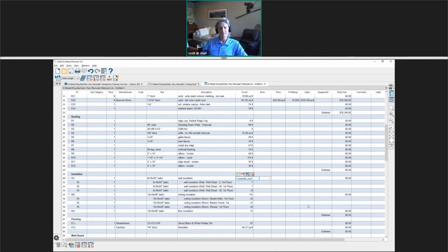And if you notice, once you do that, so let's see, what's the length in this case? Is it the 93 inches? Right. Yeah, so you can multiply that by 93 inches, and then probably divide by 12 to get it into feet. And once you do that, that little box that's just to the right of that formula will open up, and you can tell it that you want it to display that in feet, and then you can set a price per foot.